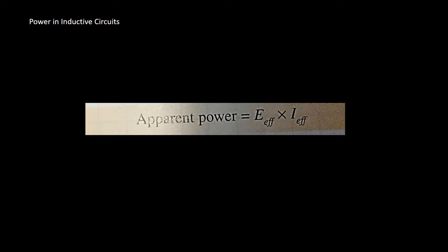However, in an AC circuit containing inductance only, this formula does not hold true. In this type of circuit, the current will flow bound by the reactance of the circuit. The power used to build the magnetic field is returned to the source when the field collapses. This is reactive power. Reactive power is measured in VARs, which stands for volt ampere reactive.